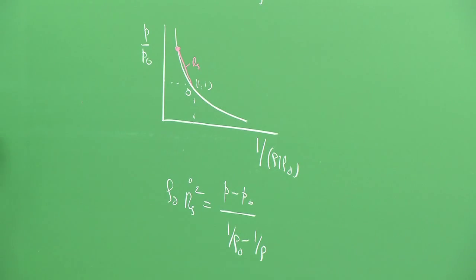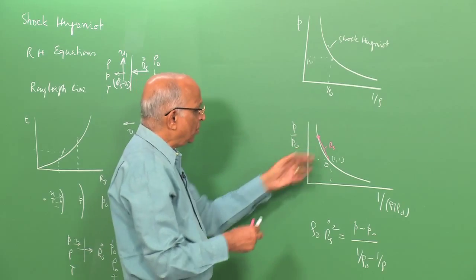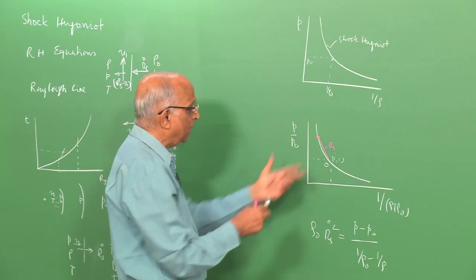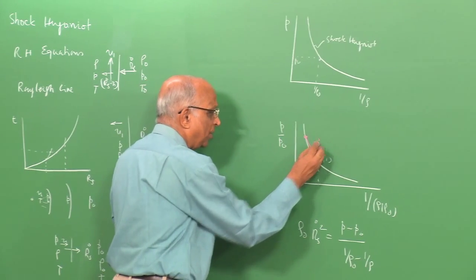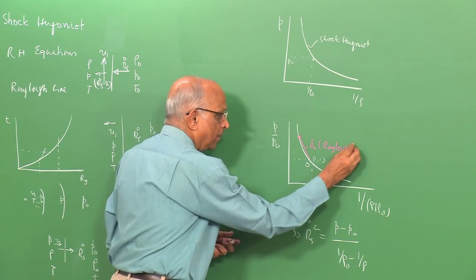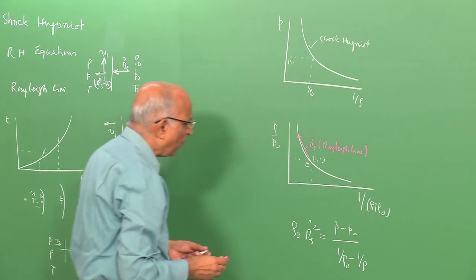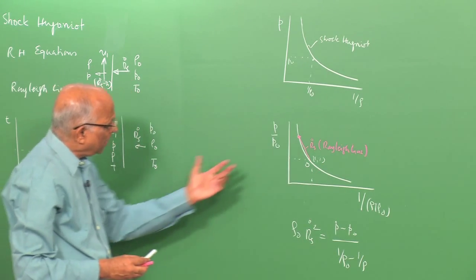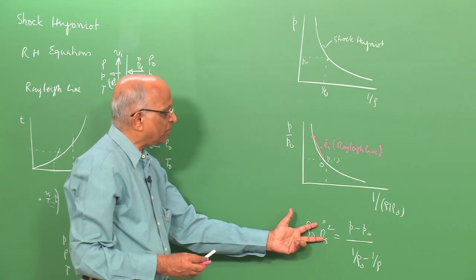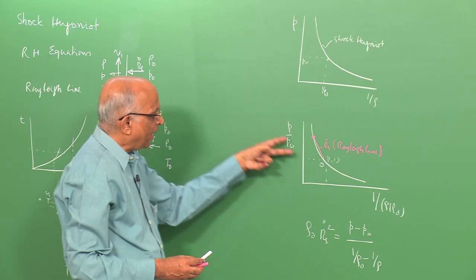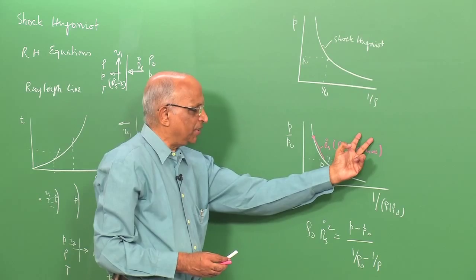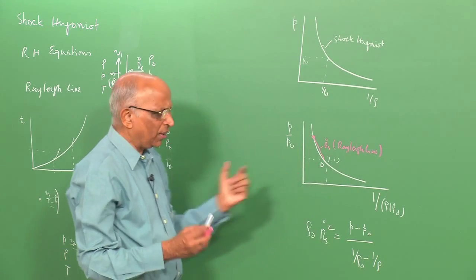Well, this was done pictorially using the Rankine-Hugoniot equations and the Rayleigh line, or the shock-Hugoniot and the Rayleigh line, which gave me the velocity of RS dot over here. Let us put it down, it is Rayleigh line over here. But I found that even though graphically I can do, can't I do the problem and get an analytical expression for P by P 0 as a function of RS dot and as a function of the initial conditions, let us say P 0, rho 0, and this is what we wanted to do.